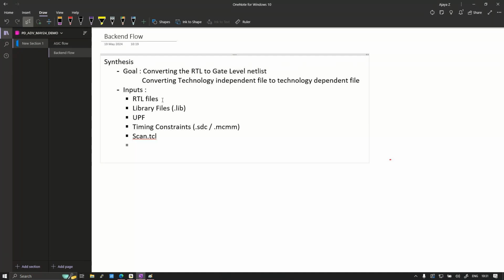As I said, timing, power, area related information, but as the synthesis I am providing is logical synthesis, area related information will not be provided. When you perform physical aware synthesis, area related information will be provided. How that area information is provided varies. So we will be focusing on timing and power over here.